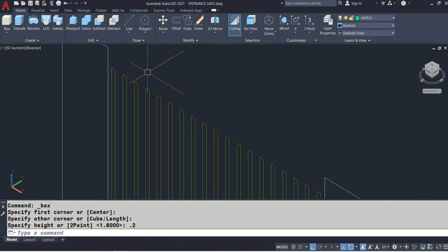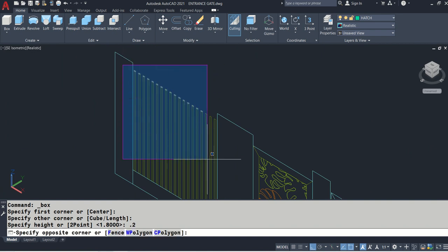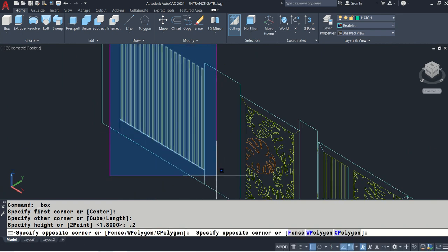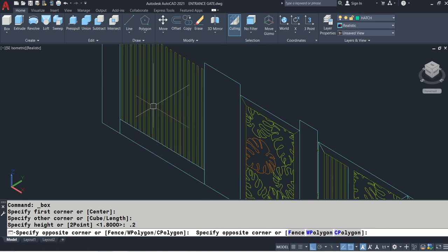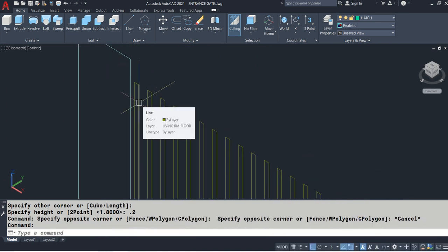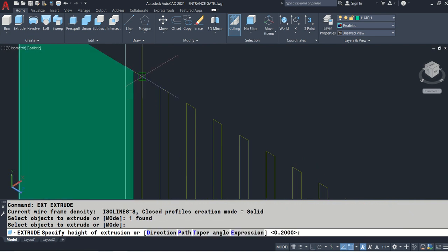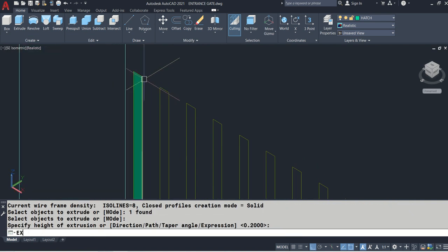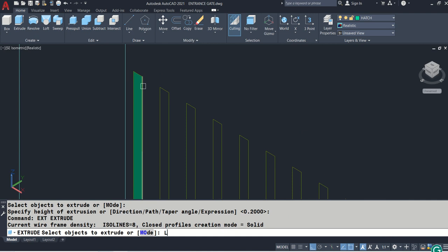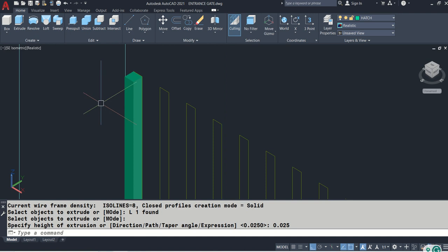And then I have this one here. I can simultaneously extrude this. I'm going to pick from here down to the lower right. Or I would suggest, let's see, probably EXT. Select, enter, going to click here. Then EXT, enter, L for last, and enter. That's 0.025, enter.